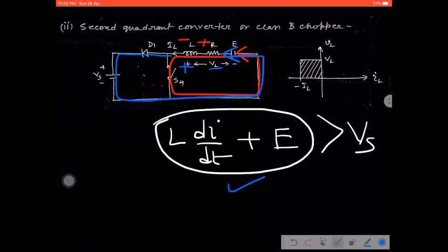That means in the charging path and discharging path, see it very carefully. When the inductor gets charged, the direction was in this direction with respect to reference, that is opposite direction, because we have taken the reference direction of the current as this one. Now the current is flowing in this path. That means opposite direction. That is why current is in opposite direction. Similarly, we assumed the voltage was this one positive and this one negative for the reference.